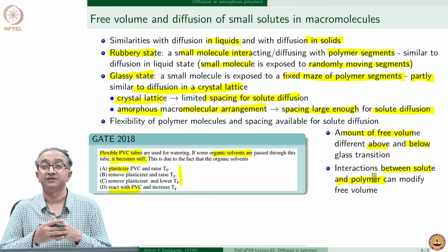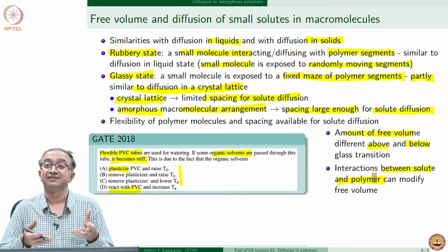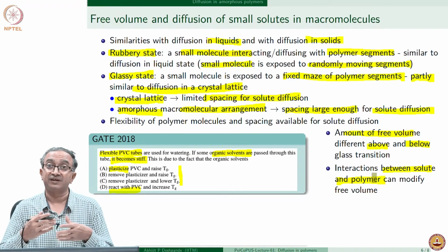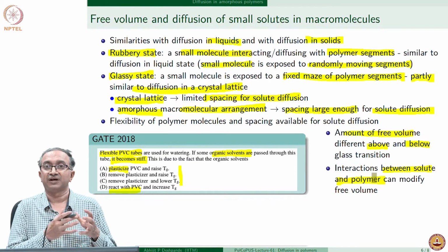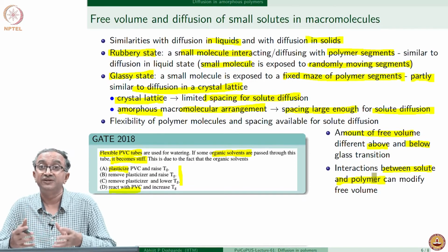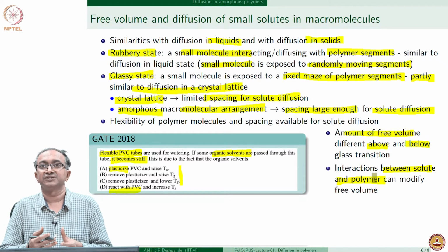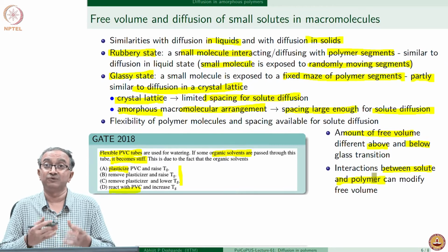water starts diffusing in, what water can do is it can plasticize the nylon macromolecules, and then nylon macromolecules can start changing conformations. And so, the interaction between water, which hydrogen bonds with amide bonds of nylon, can induce macromolecular segmental flexibility in case of nylon, and therefore, the free volume changes.